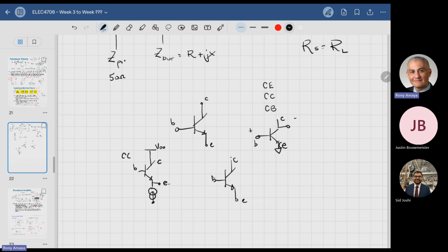And the base cannot necessarily be shorted, because if you short the base, what happens? This is an NPN device. It won't work, right? So you can't really short it. So you still have a biasing network here because you need to bias that base, right? Because VBE has to be positive for an NPN device to conduct. But I already have 2 ports committed. Sorry, 3. So I have 2 ports. I cannot afford to have another port. So how do I do it? How do we do it in 2507? How can I generate a common base?